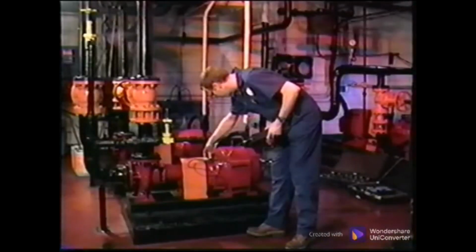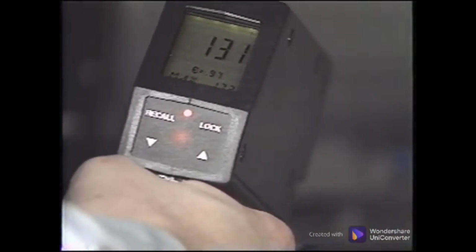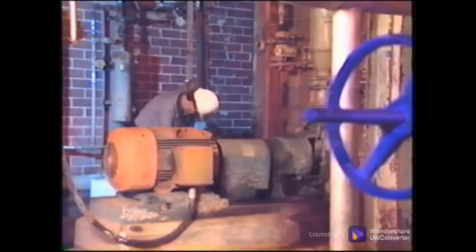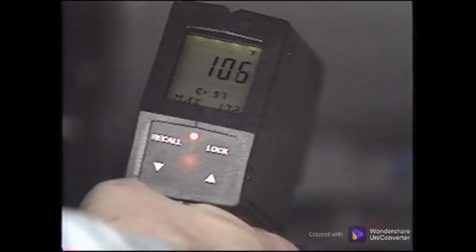Collect vibration data and other operating data. Be sure to collect the necessary data to determine the online to offline running condition. Inspect the base plate, foundation, grout, and hold downs. Notify operations and follow all safety procedures to shut down and lock out the machine. The online temperature data will be used later to help you determine thermal growth.